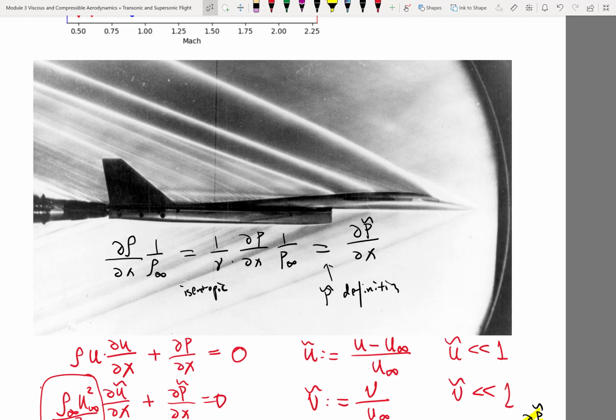If you combine these equations together, you get the divergence of the gradient of the velocity potential equal to 0. That's the archetypical elliptic partial differential equation. And the nature is that if you make a geometry, the effect of the geometry is going to propagate upstream, downstream, in all directions. That's what happens with elliptic equations.